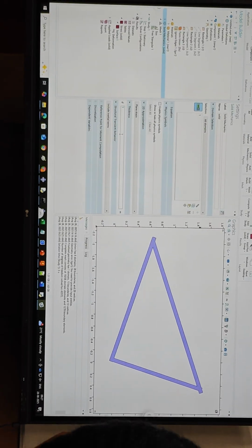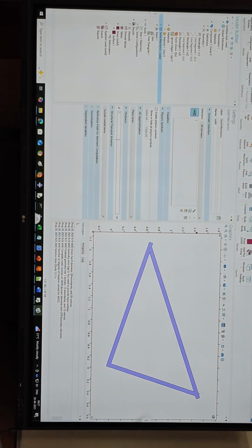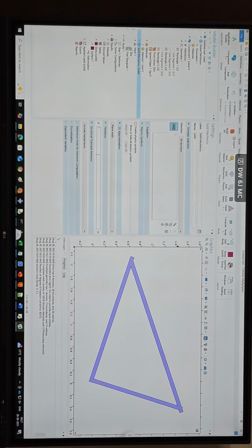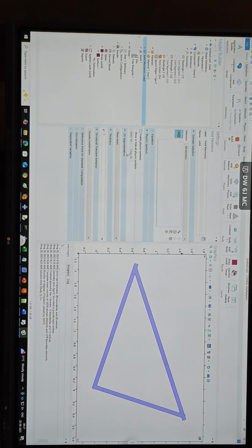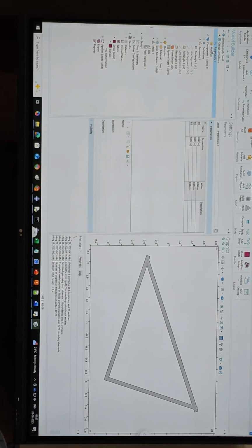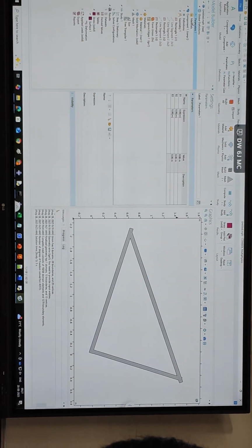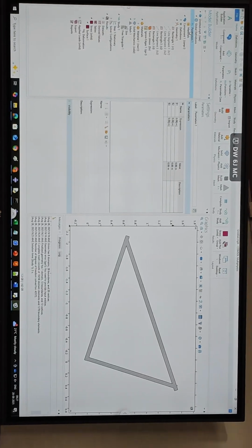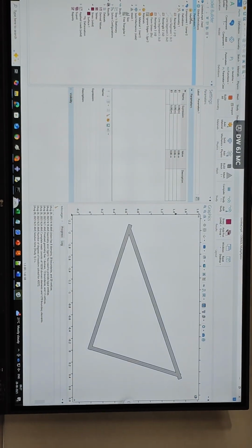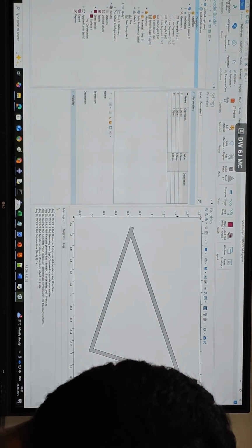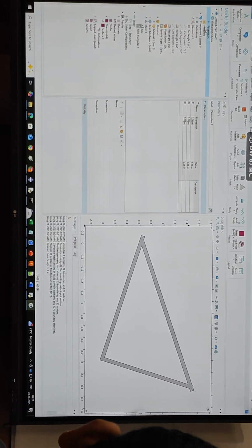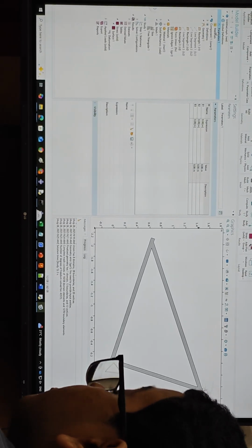Just a quick question I wanted to ask. That part I got, but we will have to add that to the system inside. I mean, like B1, B2, B3, we will have to add the square root. Okay. No. You can define the cross section how you want it to be. I'm just telling you, if you want to verify that bending is not dominating, right? You have bending included here, unlike a truss with extension and compression. So for bending, I plays a role. That is your second moment of area. Yes, of course. So you want to test that if I change the out of plane dimension and the in plane dimension, what changes?